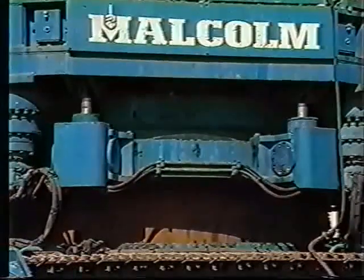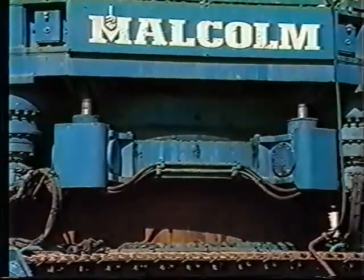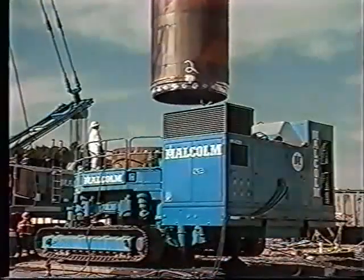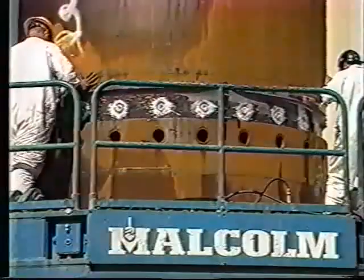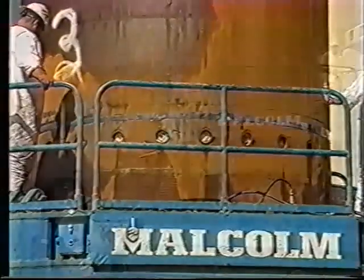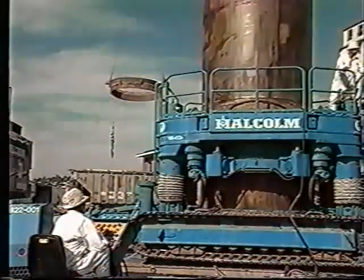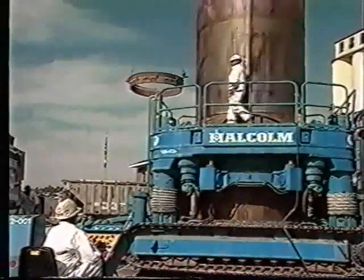The rotator rotates the casing into the ground with 5,340,000 foot-pounds of torque, easily coring and handling many types of soil conditions, from hard rock to bay muds. Additional sections of casing, 20 feet in length and weighing over 38,000 pounds, were added to drill shafts up to 125 feet in depth. The rotator has the capability to drill holes up to 10 feet in diameter and over 200 feet in depth.